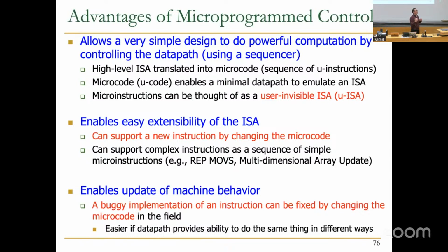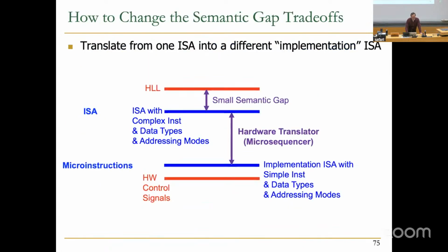And the reason they can do that is not everything is hardwired completely. There is some layer of translation like this that gives them some flexibility to translate from the ISA to micro instructions, and there's some programmability in this layer, essentially, right? And what we've kind of done is, when we were determining the control signals for every state in the finite state machine, we were really microprogramming the machine. We didn't call it microprogramming, but it's really microprogramming the machine. You set the control signals, and somebody does that, and if there's a bug, they actually fix it, and they release a microcode patch, and you download it, and your processor works better, or more correctly, or higher performance also in some cases. Okay.